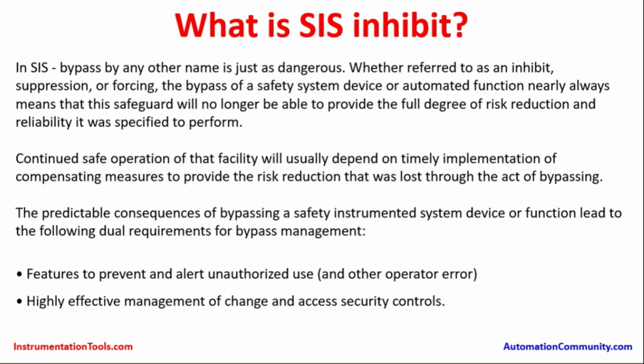For example, it's a 0 to 10 kg pressure transmitter, and at 8.5 kg per square centimeter, the trip is programmed in the logic solver. The bypass will be made in such a way that the pressure is reading around 6 kg on the particular piping or particular vessel. That is not real actually. It's not a real process.